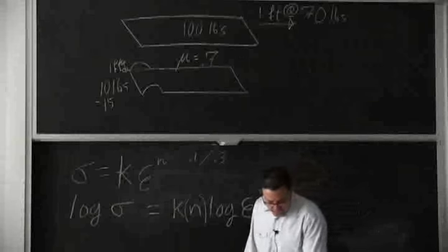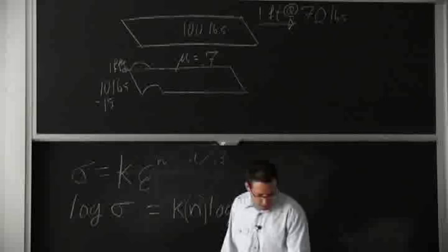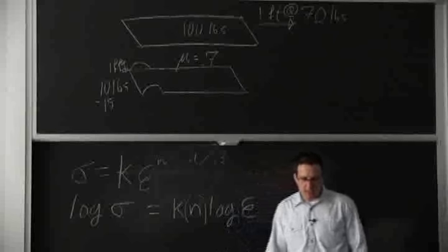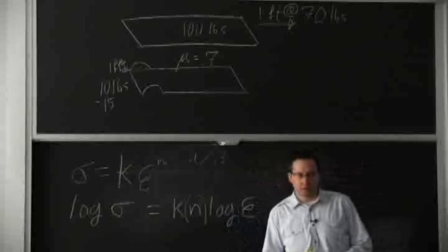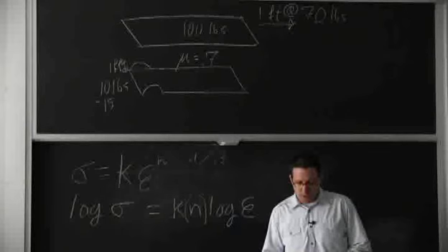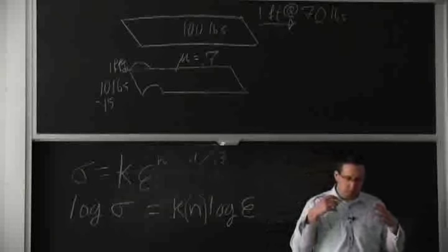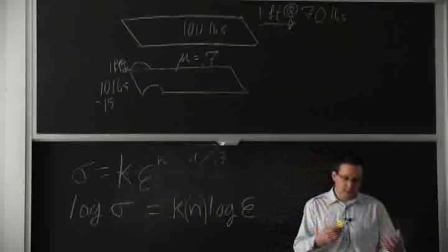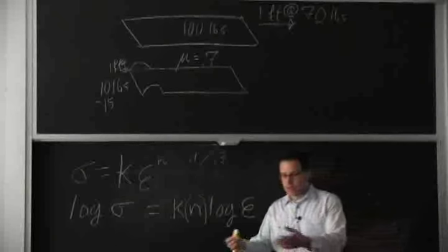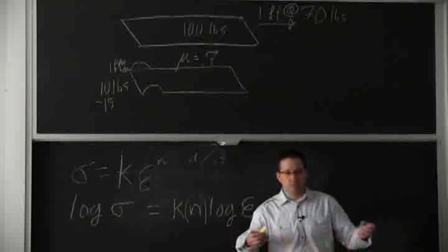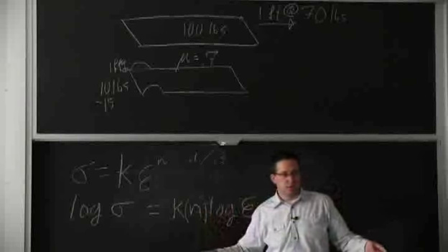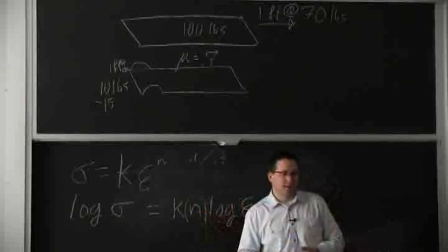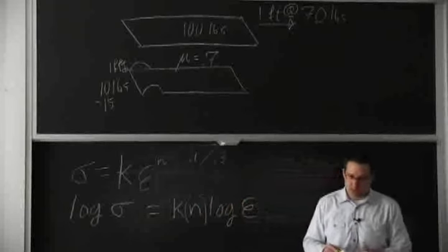Now we'll go back to what it means. The hardening allows for strain redistribution, which is good. It means that you can rely on the material becoming stronger locally, so the strain goes in a different direction and you change the shape, and when you bend the bar, a lot of times it'll have a nice curvature as opposed to having a kink in it, a solid bar.